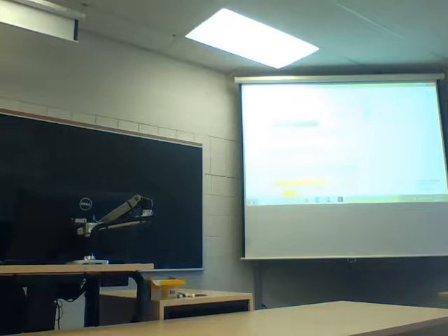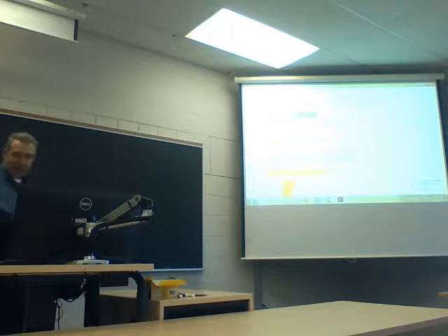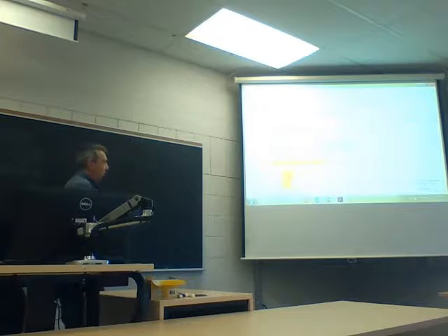All right, let's get to the good stuff. Reciprocating compressors. Reciprocating compressors are made of a variety of design arrangements and divided into types according to single stage, two stage, tandem, and free piston. In my experience, reciprocating compressors in our power plants are being taken over by screw type compressors, but there still are a lot of old plants out there that use reciprocating compressors. They're a go-to. They're wonderful. Great compressors. I was trying to take one apart, see how it works, pull the heads off them.